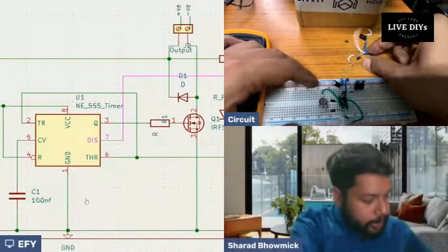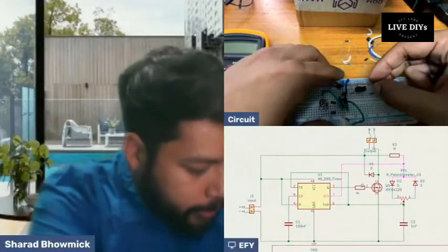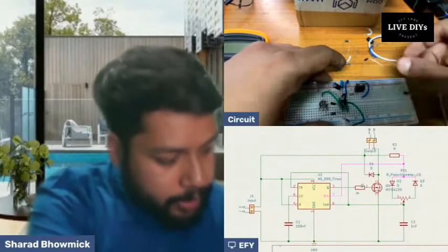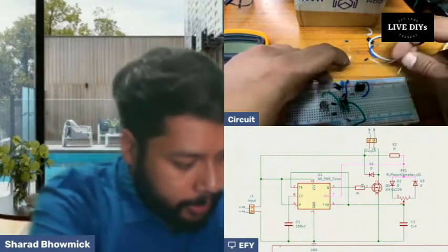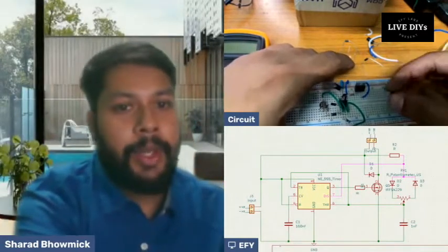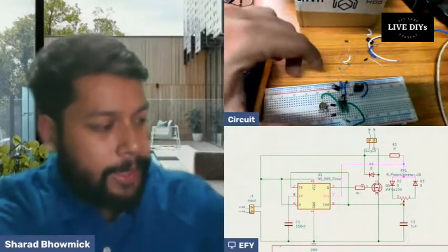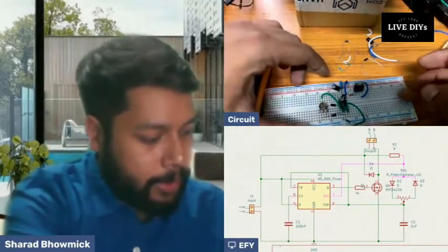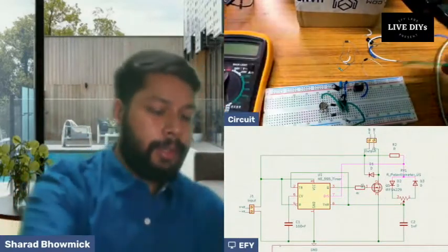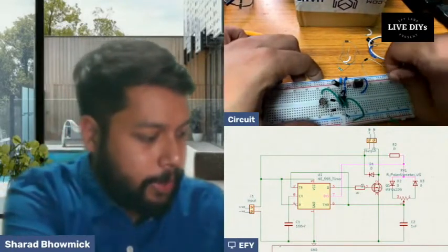Okay, we need to connect the negative terminal to the ground of the MOSFET. The drain of the MOSFET should be connected to the ground, and the positive terminal, actually that is not needed, but we can connect it if you want, to make sure that it doesn't affect the motor, but we can run it without that as well. Now I'll just power the circuit. We need to connect it along. So now I'll use our battery to power the circuit, which is providing 12 volts.